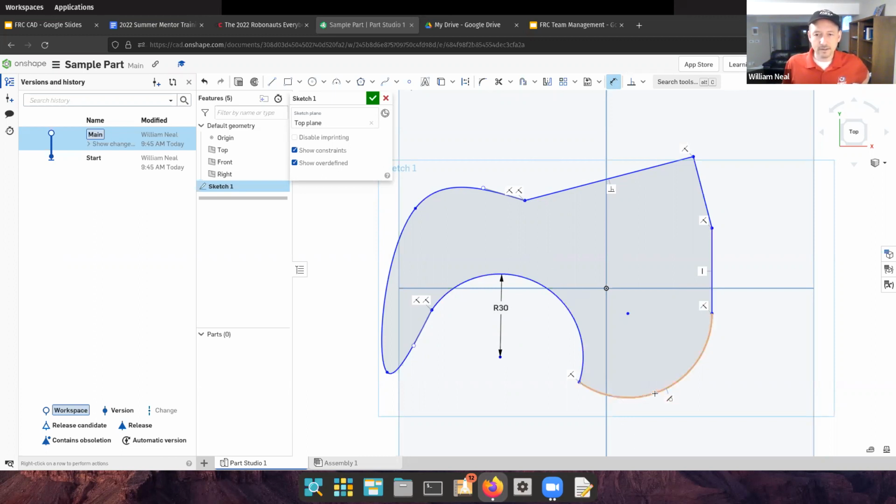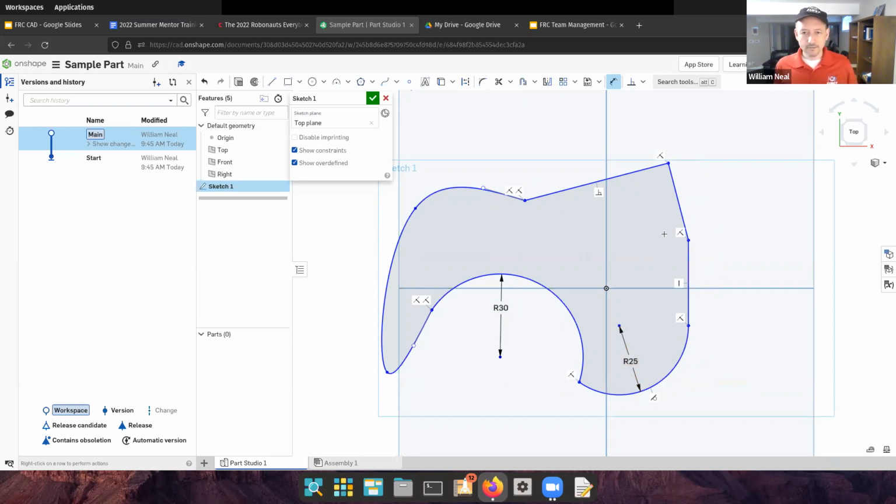But now what about this one here? I have not specified any other dimensions except for this radius. What if I try to specify this radius? At the moment it's 30. I click here and let's try making that 25. Will it still be able to do that? Yes, it just shortened the line to achieve that 25. And finally here, one thing I can do, you see here from this line to this line, it looks for the moment like this is just tangent to this one and it just has the same angle. But if I were to drag something, I'm just going to escape out of my tools and take a point.